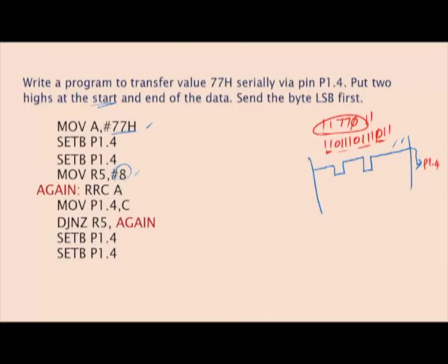The accumulator is now rotating right. So, rotating right through the carry means the first bit will be transmitted. So, bit by bit it is transmitted via the carry. So, the carry flag will move to P1.4, right. So, like that you have this kind of information, right. So, for these 2 we have already transmitted. So, now only these 8 bits I am going to transmit.